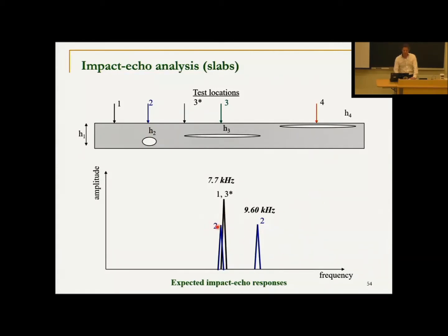But we also see a lower frequency too, because not only do we see this vibration above the hole, but we see the entire vibration like we would here. And this is a vibration method. And this vibration is a little more compliant because a hole is there, right? Now if we go to point 3, you see, aha, it's now becoming more shallow and we're getting higher frequency. And here we don't see that same kind of leaking full resonant mode anymore because all of the energy is trapped within this membrane here.